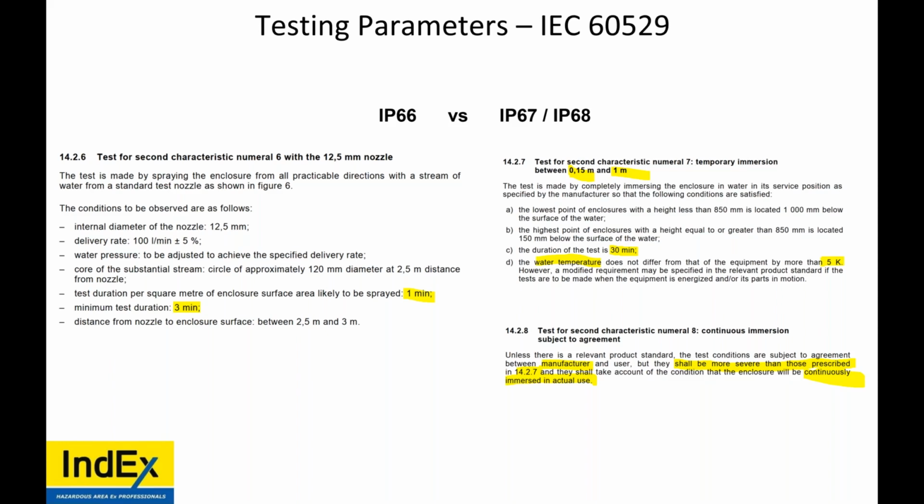But if it fails IP66, if that's only the 3-minute test, it's not very good. But do others test for longer periods of time? Yes, they do. The test involves 3 minutes of the light being on. Then they open it up and see if any water was drawn into it. But it's only 3 minutes on a new piece of equipment with brand new seals.